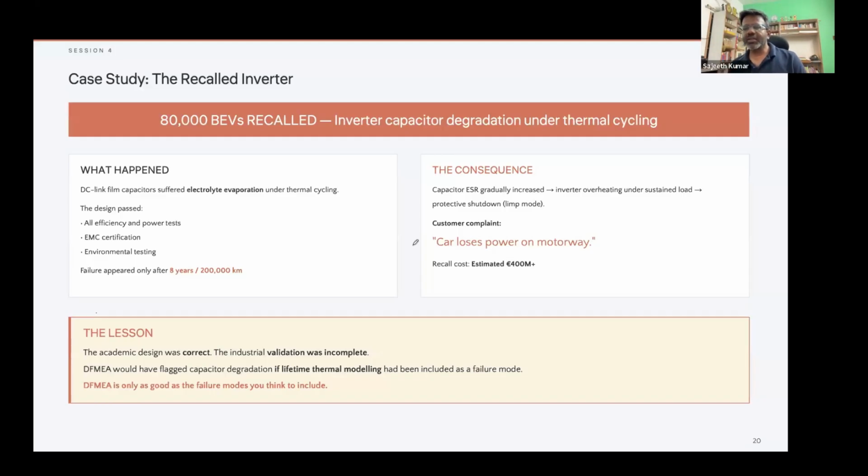Okay, can you develop a systems engineering model for predicting failures? Yes, you can, right? So how would you do it? All you'll have to do is, I mean, I say all you'll have to do, but it's not that simple in terms of the effort involved. First you draw your architecture, right? You have your motor, you have your MCU, motor control unit, connected to your battery. When I say MCU, I mean MCU plus inverter, the integrated thing. You have the battery, you have the BMS, right?